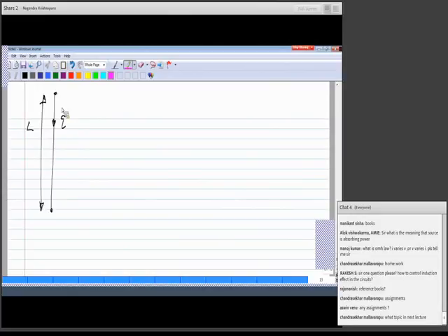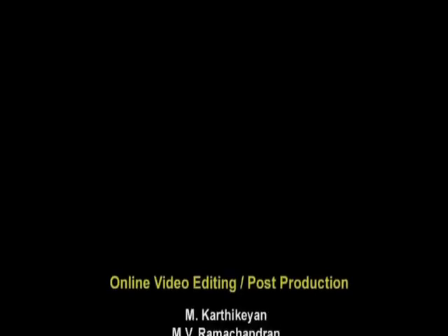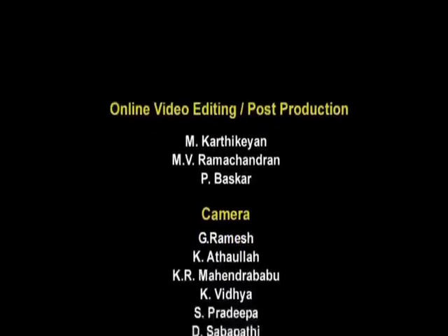Now we will only be talking about those situations where the dimensions of the circuits are much smaller than the electrical wavelength of the signals that are driving it. So in our cases, Kirchhoff's current law will be valid, and similarly for Kirchhoff's voltage law. So in general, these things can be violated if you have a very large circuit in relation to the electrical wavelength, or in general if you increase the frequencies of the signals. Any questions?